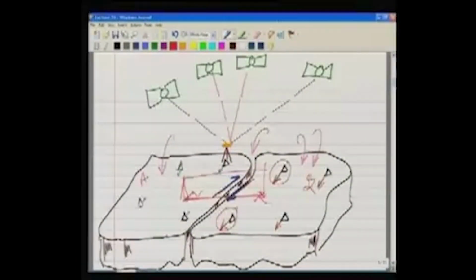In this case, this landmass as well as this landmass both may move. If the movement is the same in the same direction, the vector between two points will not change. But in the case of the GPS, each GPS point is being independently measured with respect to the satellites, and satellites are not going to be affected by slight movements of the land masses. So this is a very important technique and is being used.